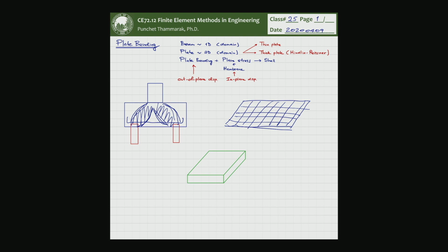So your design will be automatically conservative. The steel required in a design like this will generally be more than in the strut and tie model design. This is widely used in several programs for foundation design.